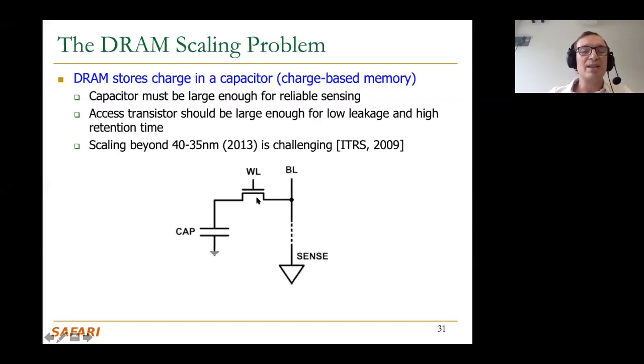But basically, it doesn't look two-dimensional like this. You have this transistor, let's say in the planar XY dimension. But now imagine this capacitor being etched into the Z dimension. So in a sense, you have this transistor, and in the Z dimension, in the three-dimensional view, a capacitor's length is about 70 to 90x the length of an access transistor today. I will show you a picture of this later when we talk about DRAM in a little bit more detail. So that's the extent of things that are happening in DRAM today.